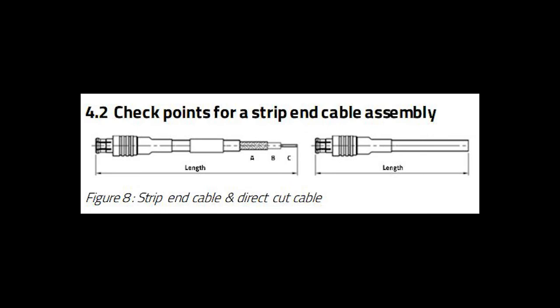The tinned braid avoids splay or damage during transportation, and it's easier for assembly. And finally, there's the tinned center conductor. The tinned stranded center conductor is helpful to prevent damage during transportation. It also makes it easier for assembly. But an open, exposed end of the assembly should be taken into consideration to avoid the risk of crimping or vibration applications.